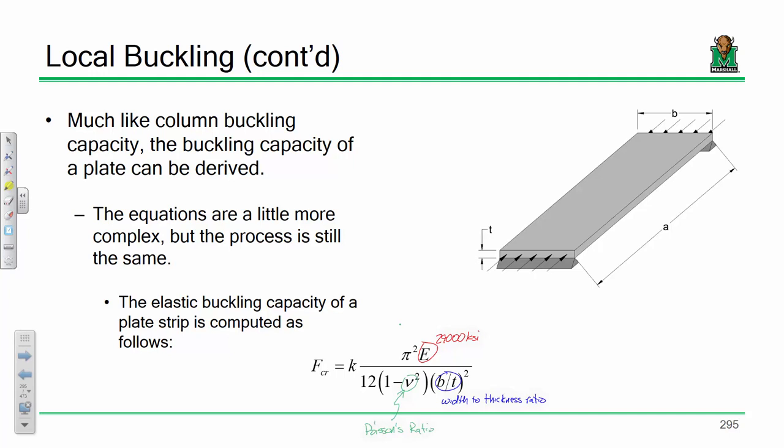Now, does anybody remember what Poisson's ratio is, like behaviorally? Exactly, it's exactly right. So if you have, let's say, a rubber band or a piece of taffy, and you yank on it, not only does it get longer, but it gets thinner. And vice versa, if you press it, not only does it get shorter, but it expands. Okay? And the ratio between the strain that you get laterally versus the strain that you get longitudinally is what's called Poisson's ratio. Now that is a material parameter.